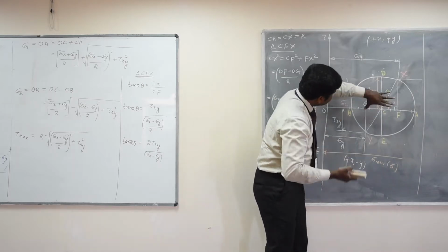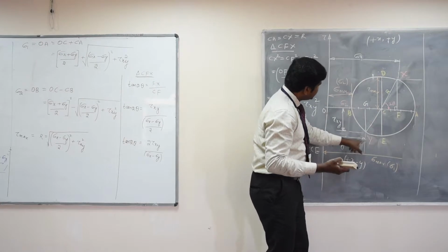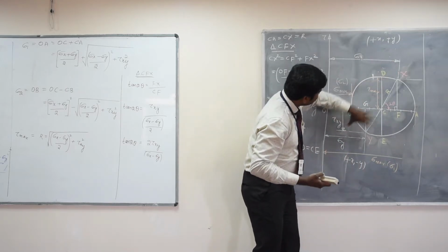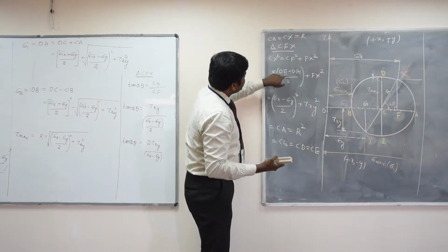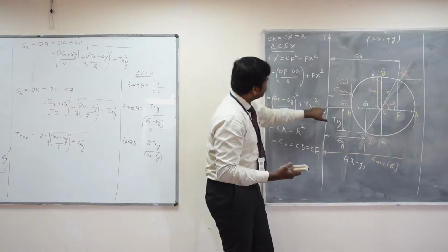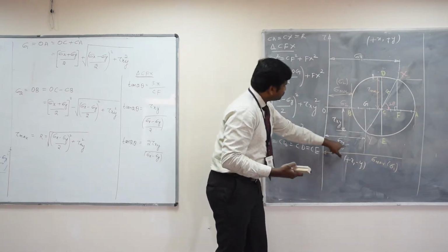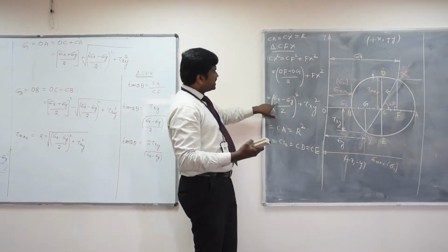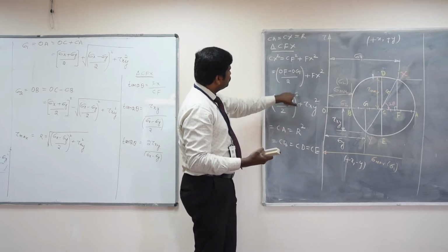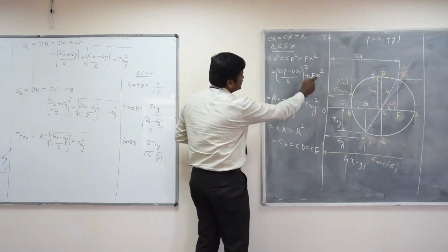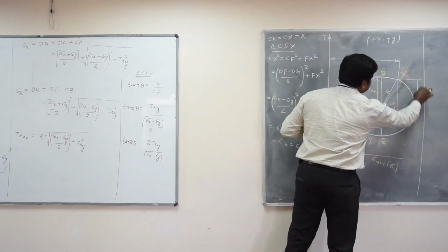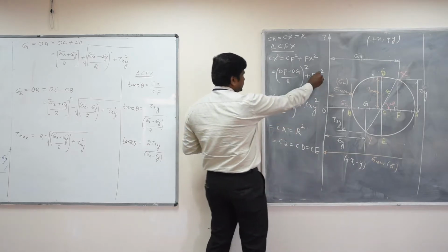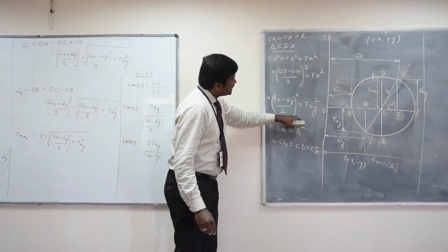That means if you know this distance, half of this distance will be CF, because the distance of the tau xy will be the same from the horizontal axis. So we are taking sigma x minus sigma y, so that you get this distance, half of that, that is CF. OF, which is sigma x, minus OG, which is sigma y, by 2, because we want half of this distance, whole square, plus FX square. FX is tau xy, so tau xy square.